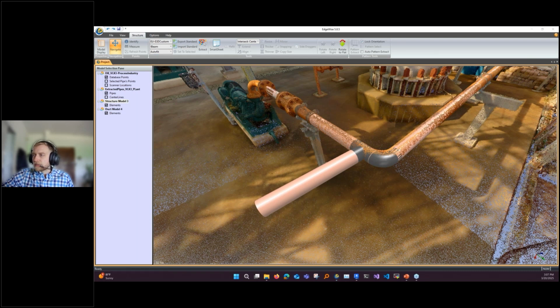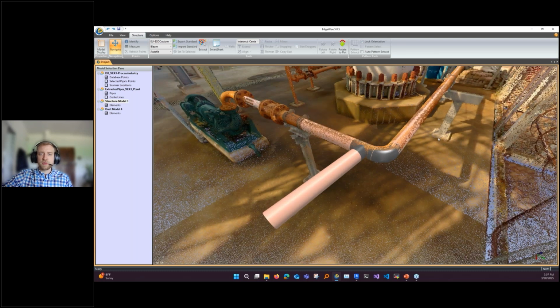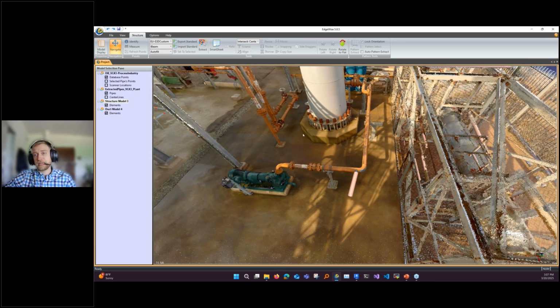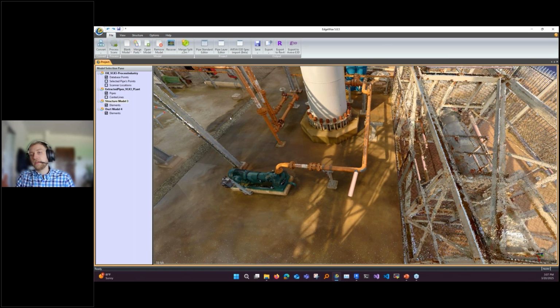Okay, modeling above ceiling, stat areas. So above ceiling is tricky for sure. I think there are some different ways to approach it. Something I do suggest sometimes is that the manual tools can be really nice on their own. We obviously push and suggest using the auto extract a lot, but there is an advantage to just making a new, blank pipe model. For stuff that's really congested, it may be better to just model by hand. If you are dealing with a congested above ceiling, an option is to run extraction and then delete everything above and below the plenum space. That could be useful to help clean things up, but that is a tricky one.